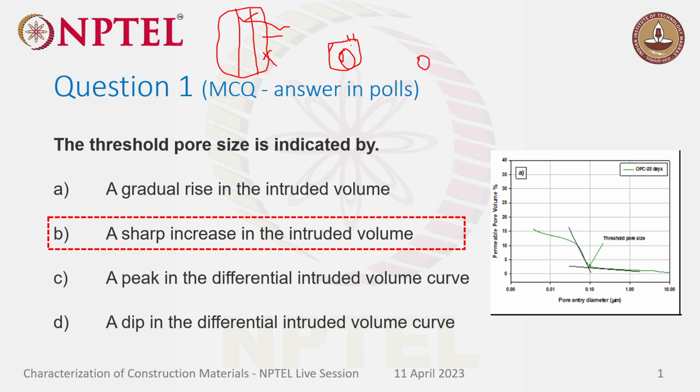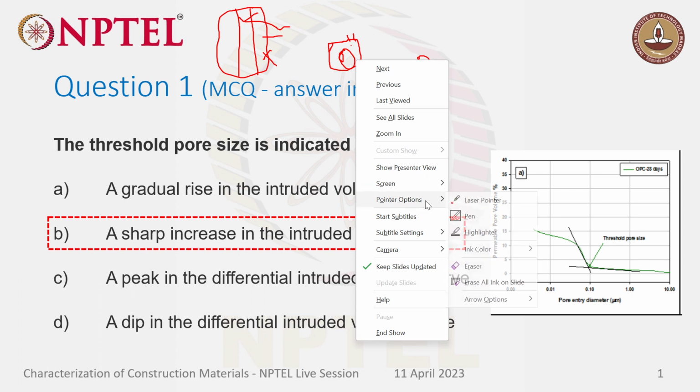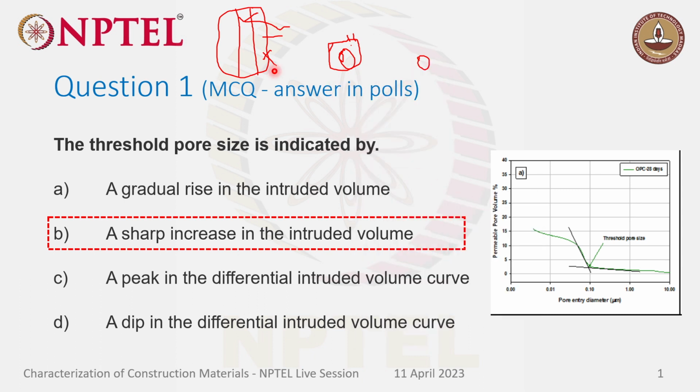So we should understand why we are doing the characterization. In that way you'll get to know where we have to take the sample from. If we have to compare two different cement systems and only the effect of curing or how the reaction kinetics has been affected, you have to take the samples from the center of the cube. And if you want to understand the chemical phenomenon or attack or carbonation, then you have to take zones which are affected and zones which might not be affected, and you can compare. Okay, ma'am. And when it comes to repetition, mostly we don't repeat.